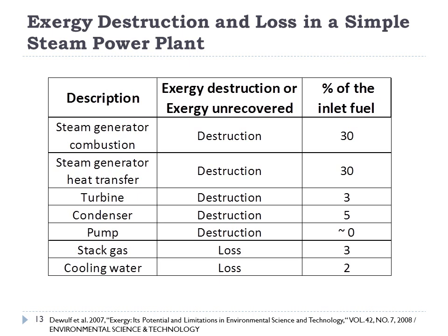But if you go to the other extreme and try to get every last drop of exergy out, the size of your heat exchangers becomes enormous, and then your capital cost gets really high. So when you optimize for return on investment, you find there's some optimum in the middle, where you allow some gas to leave, but you don't let all of it. You don't want huge exergy remaining in your stack gas.